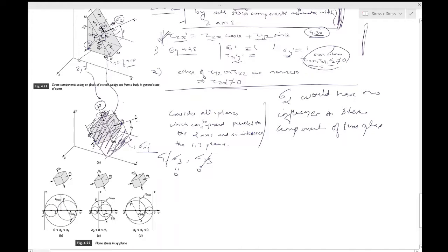We are now discussing a situation in which this circle is drawn, where sigma 1 is greater than sigma 2, which is greater than sigma 3, which is equal to 0. Now these are the two circles which have been drawn. Finally you can obtain a third Mohr circle which represents stress components on planes parallel to the 1 axis.